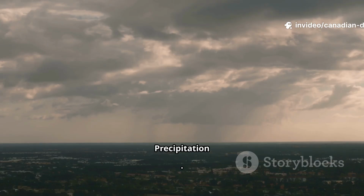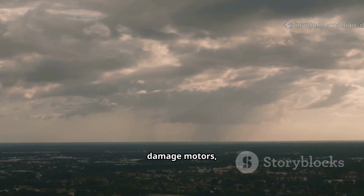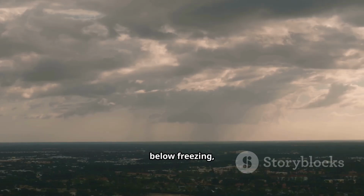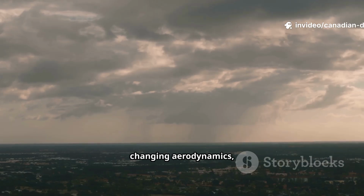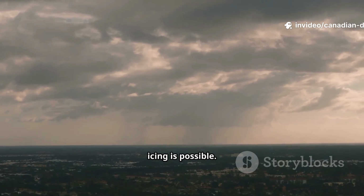D. Precipitation, loss of water damage. Drones have numerous vents and are not waterproof. Moisture can short-circuit electronics, damage motors, and obscure cameras and sensors. Icing: in temperatures near or below freezing, moisture can freeze on the propellers and body, adding weight, changing aerodynamics, and causing a crash. Do not fly in conditions where icing is possible.